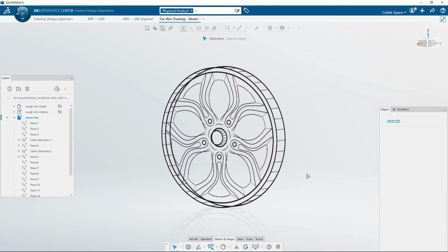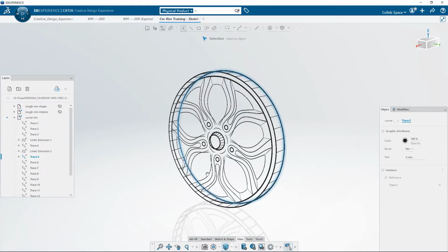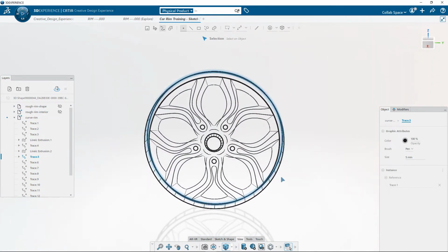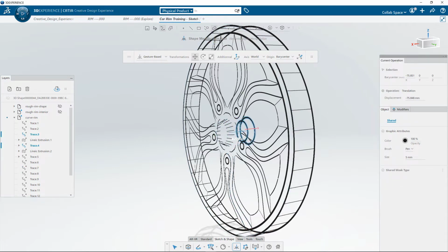Until now, I created curves by drawing them on a 2D plane support, and I want to transform this curve network into a 3D dimension sketch. To do that, I will use the transform command to manipulate each curve into the X direction and give volume to the full sketch. I start by moving the center circle and its linear extrusion with transform command and the object selection filter activated.